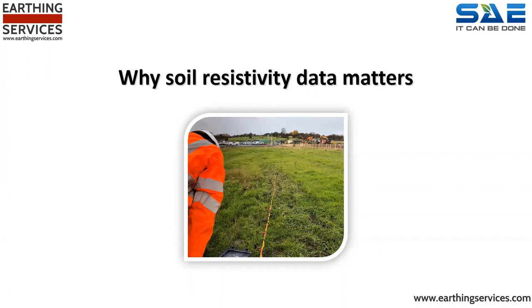But this is no comparison to the professional approach. The only thorough, scientific and logical method of determining an electrical earthing system is to undertake a complete soil resistivity survey to an approved methodology.